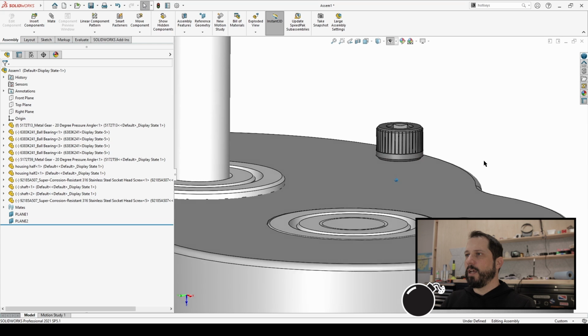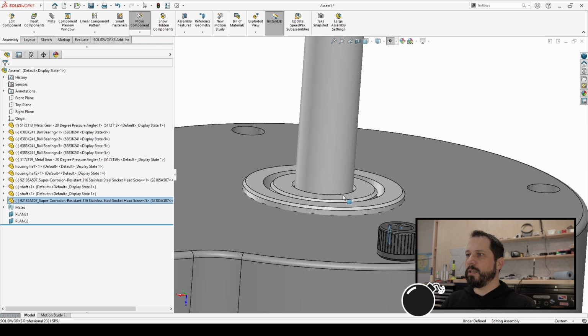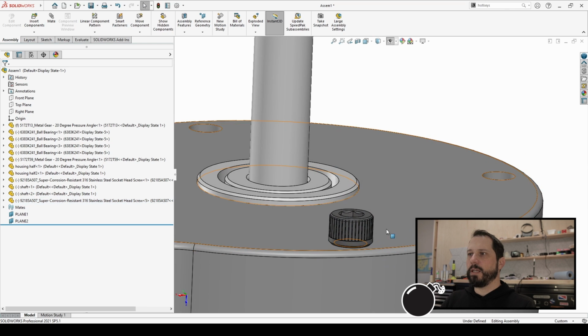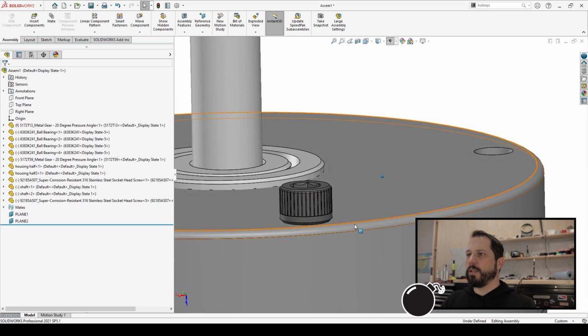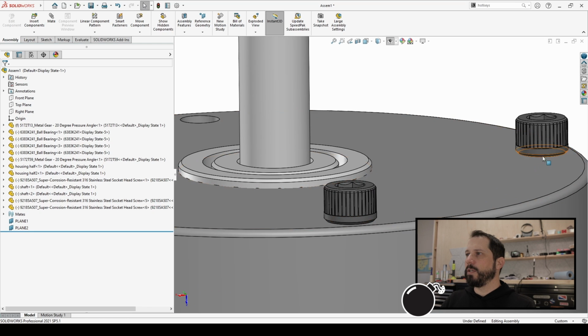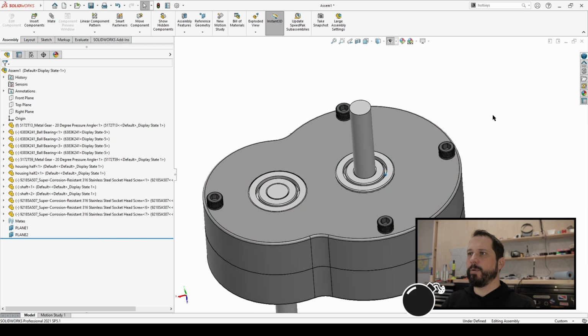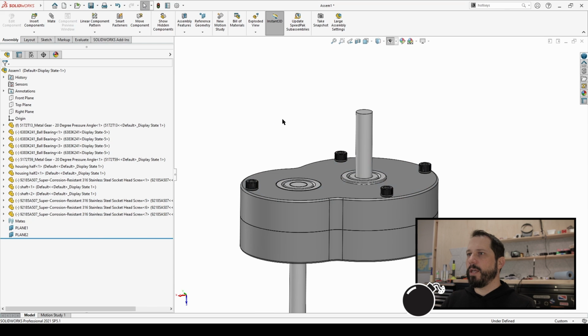and then I let go of the mouse and the keyboard, and now that screw is multiplied and it is actually mated in that hole, not rotationally because the original one wasn't, but it's mated to the face and to the hole. If you can position your model so that you can see a bunch of holes, you can just really quickly grab, install, super quick. Love that one.